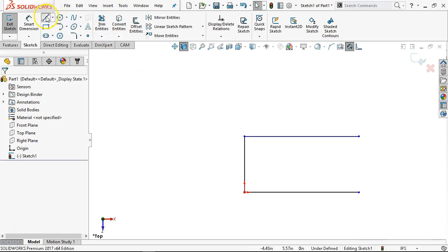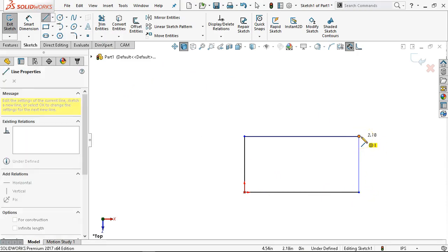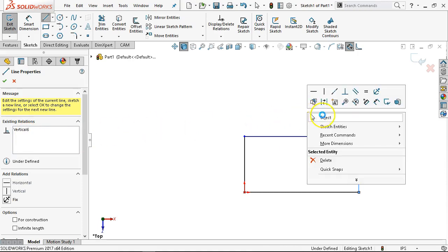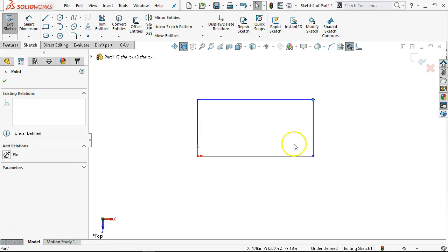So it didn't apply a relation, it just said you're there. And if I go back into line and connect those 2 dots, then I'm seeing the little yellow box that is showing me concentric, which is really a merge, and the vertical line that it will add a relation, as opposed to the coincident to the merge, which just merged the endpoints. You got what you got.